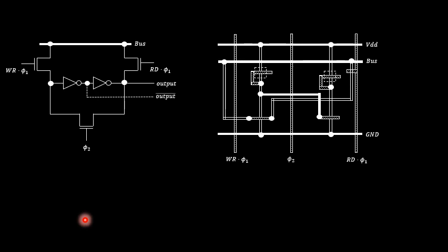So in order to avoid that, we are going for the concept of static memory cells. In case of static memory cell, we will be discussing the pseudo static memory cell. In this case also we will be using both concepts, that is NMOS design as well as CMOS design for a pseudo static memory or a register cell. If you see this particular diagram, it is a pseudo-static memory cell circuit diagram in NMOS design style. As you are seeing only NMOS transistors in this circuit, it is the NMOS design style for a pseudo-static memory cell.